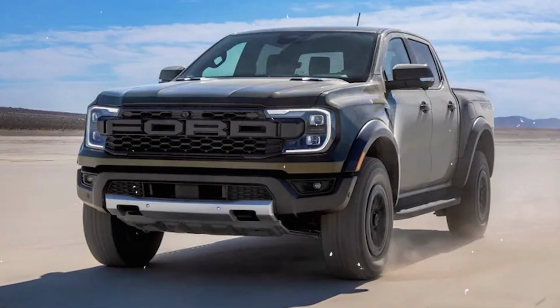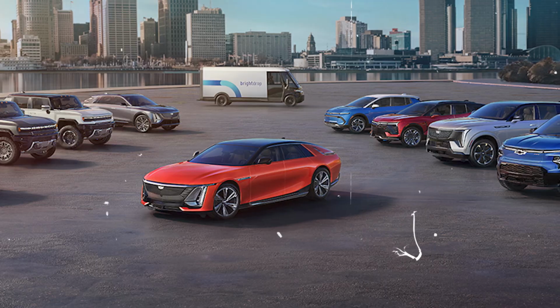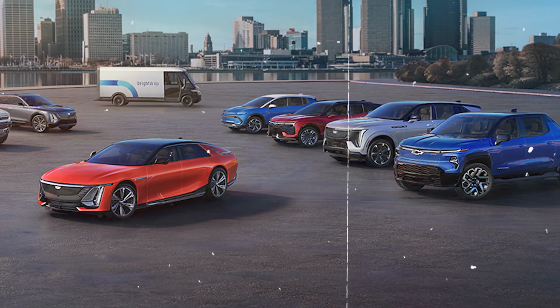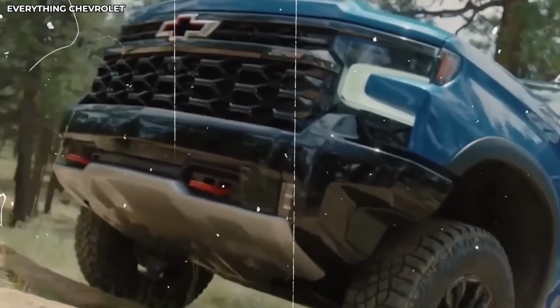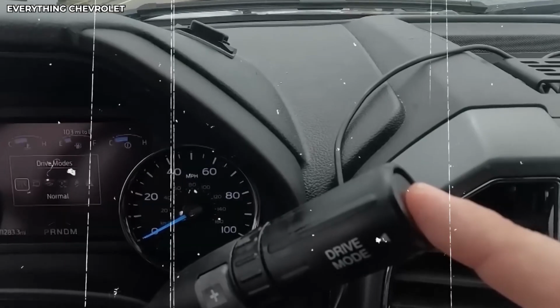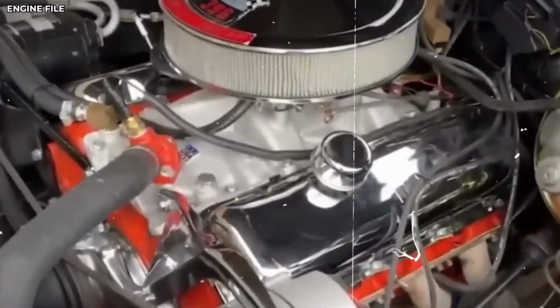Modern Fords use electronic throttle control, sometimes called drive-by-wire. There's no mechanical cable connecting your gas pedal to the throttle body anymore, like there was on older vehicles. When you press the accelerator pedal, you're not physically opening the throttle plate. Instead, you're sending an electronic signal to the engine control unit requesting power.